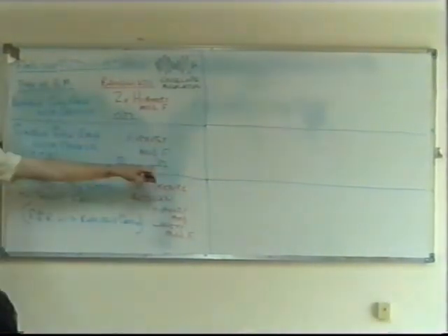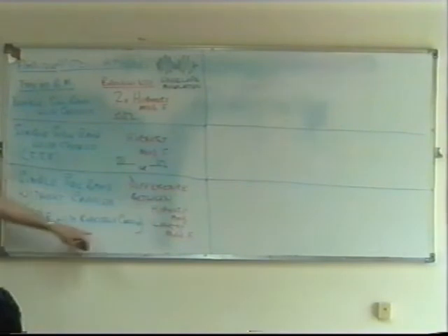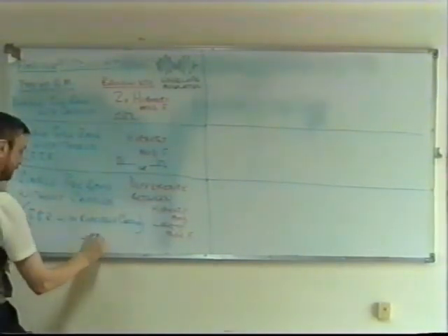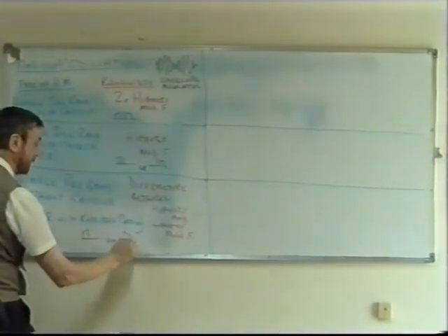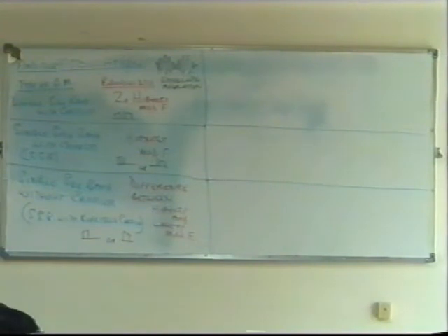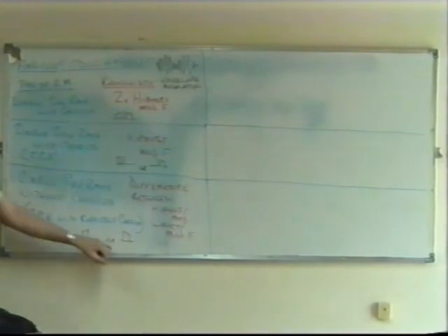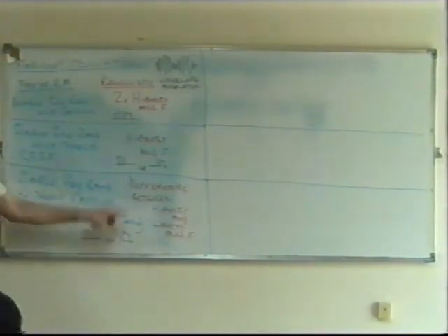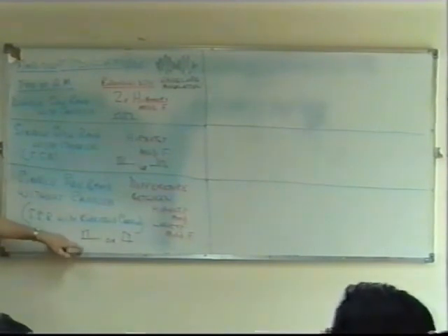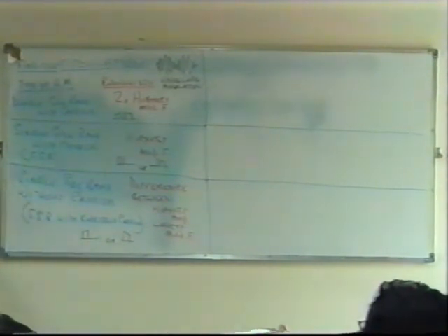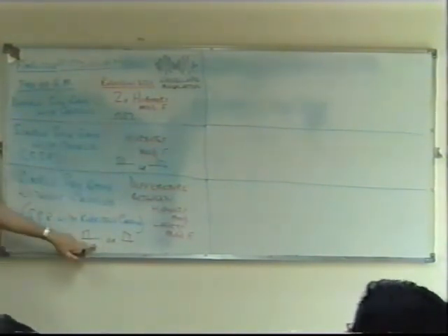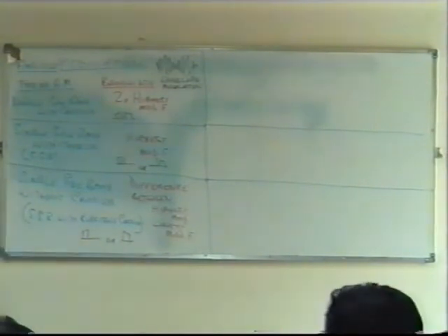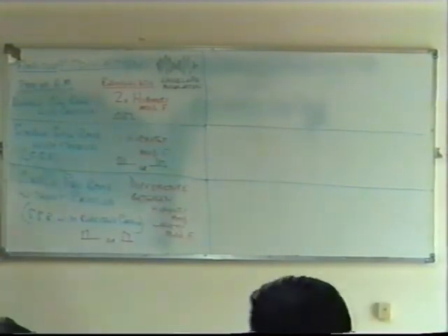Do you see what these little drawings are? Okay, now this one is either this, but without the carrier, or this. Whether it makes much difference on bandwidth depends on your lowest frequency of modulation. It might not make a lot of difference. But you see the difference in each of these. The first one will be 40 kilohertz, another 20 kilohertz, 15 kilohertz, in that example I've given you. In those examples, that's exactly what it would be.